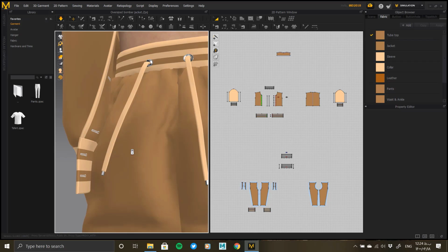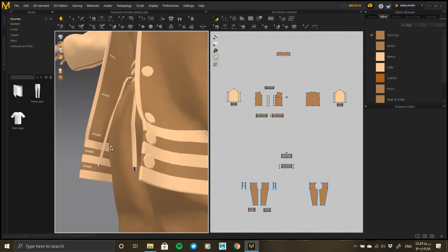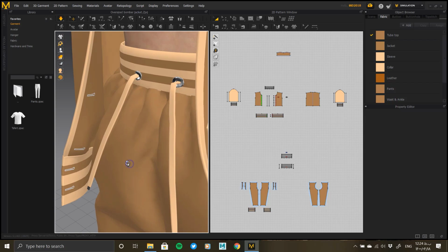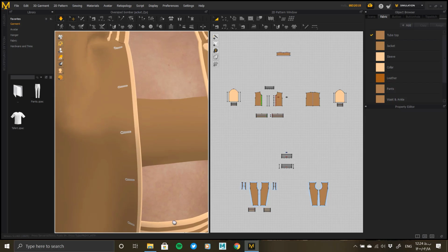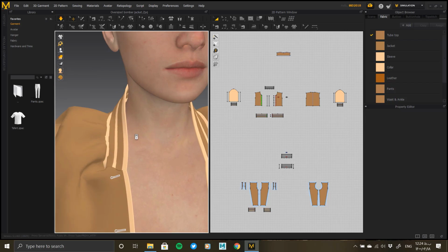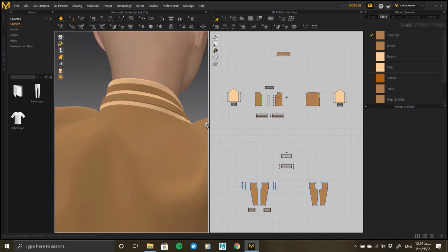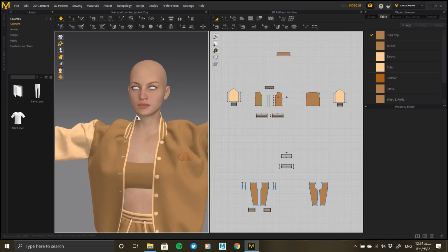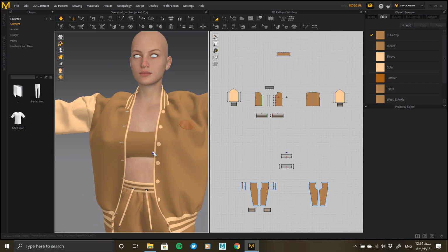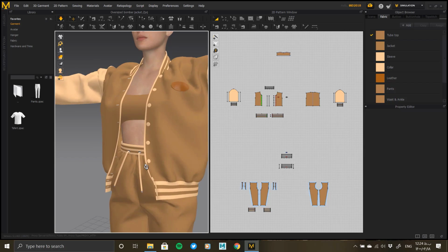We apply the material on the UV of the garment, so we need the output of our work to be unwrapped. We can use specialized unwrap software to do this, but I'm doing it here in Marvelous Designer, because I don't want to complicate things too much. To do this, at the top, change the toolbar to UV Editor to enter the Unwrap toolbar.